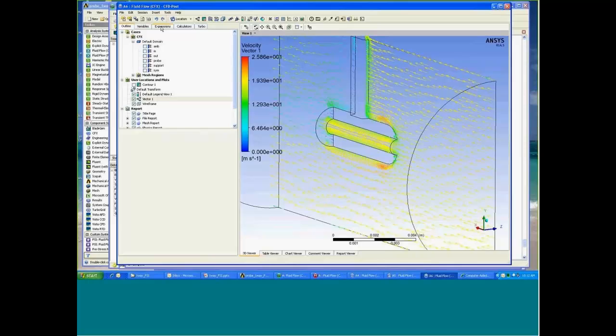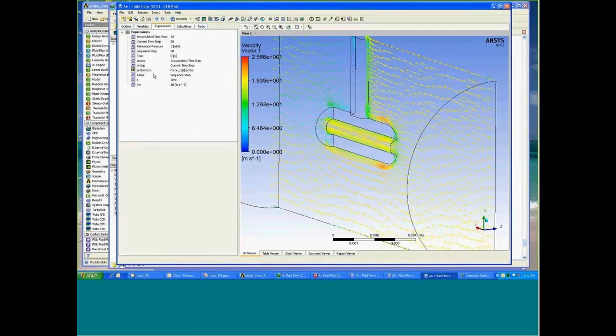As the output parameter, I defined the probe force acting on the probe. I can use that as a Workbench parameter, and later as the parameter to optimize the design in the design optimization or design iteration analysis, right? You can set this up easily.